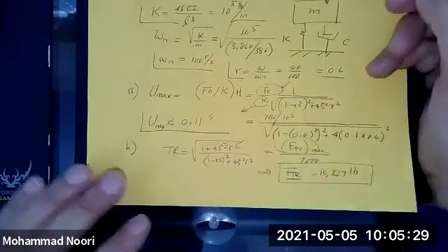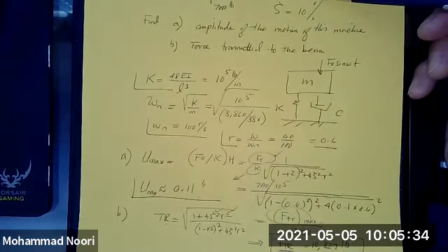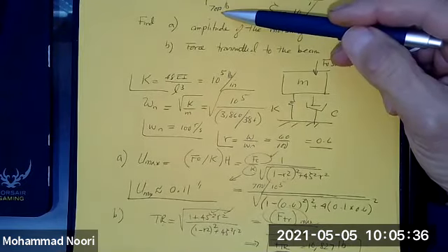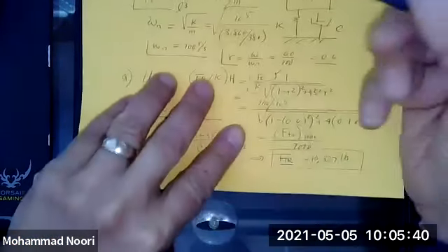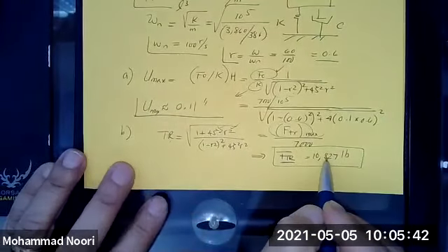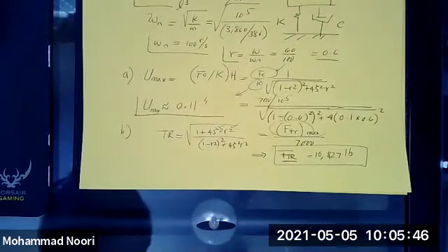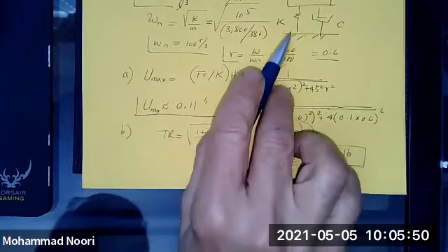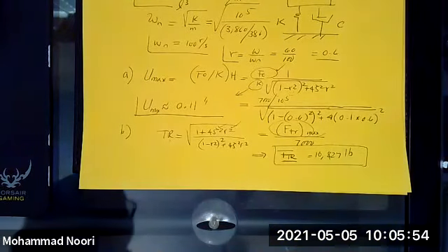So due to the action of this rotating machinery with that frequency and the force of 7,000 pounds, you're actually transmitting a force which is much larger than the maximum applied force. So what do you need to do? Increase the stiffness of this system to reduce that force.